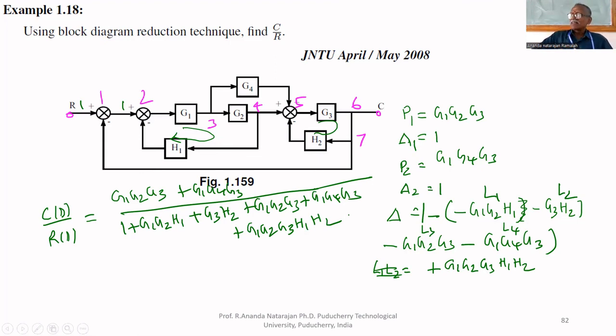First time, you try yourself with the block diagram reduction technique. So this we have to move. If we move 4 to 3, or 3 has to be moved to 4, you can do as you wish. If you move 3 to 4, what will happen? G2 is not there. Therefore, G4 by G2 you will get. If you move 4 to 3, what you will get? G2 is excluded. That's why H1 will be multiplied by G2. That's all. Anything you can do.